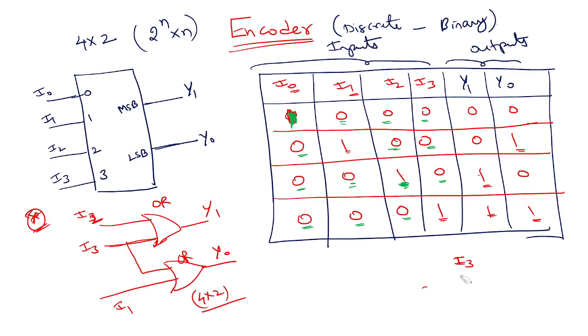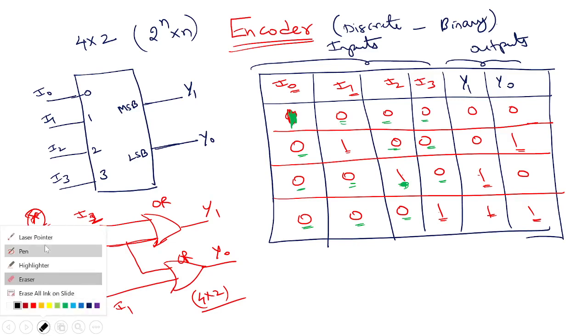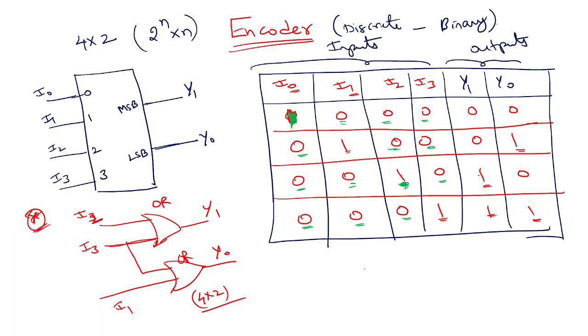You have encoders in your systems, in your laptops, where you have a keyboard. When you press something, something will be encoded and inside something happens. Let's see, for example, if I take 0, 0, 1, 0 as input, I0, I1, I2, I3. What is the output? Y1, Y0 is 1, 0, right? Now, this is what I expect. For some reason, this I3 got corrupted. So if I write 0, 0, 1, 1, what is my output? Y1 and Y0 is...